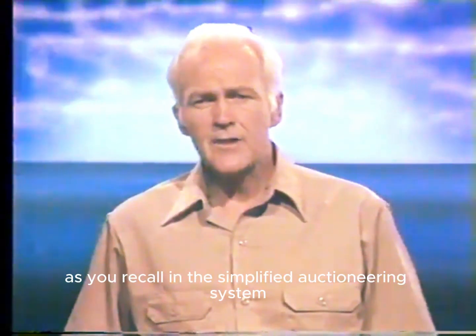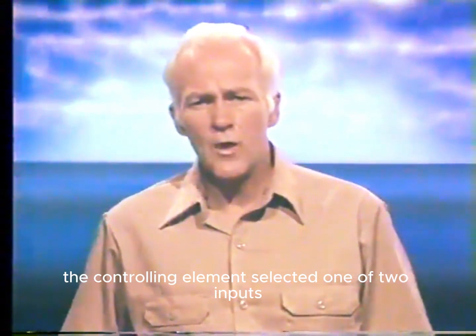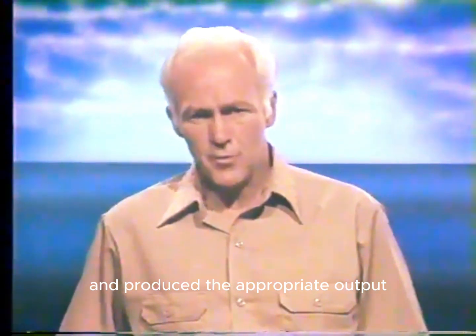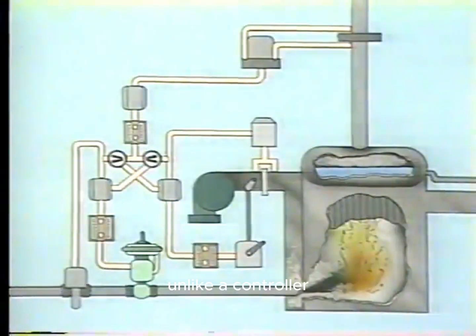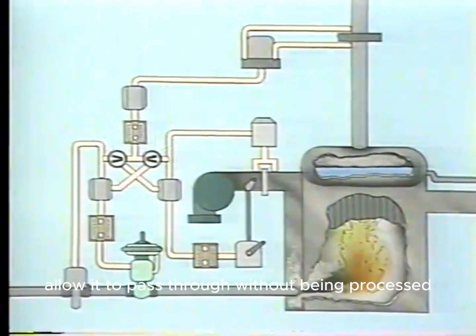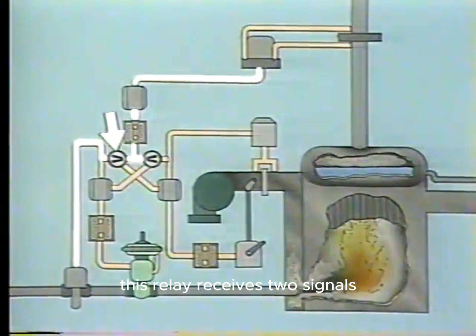As you recall, in the simplified auctioneering system, the controlling element selected one of two inputs, compared it to set point, and produced the appropriate output. Unlike a controller, the relays in this system do not have a set point. They select one of the signals, allow it to pass through without being processed, and at the same time, they block the other signal.